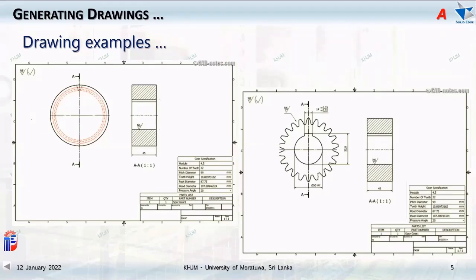Even if you add additional zeros, for example, 10.5 is not the same as 10.50 or maybe 10.500. They are all different. Numerically the value is still 10.5, but for manufacturing there's a huge difference.